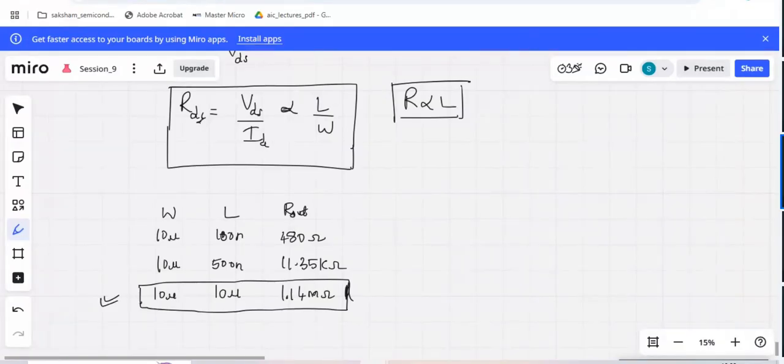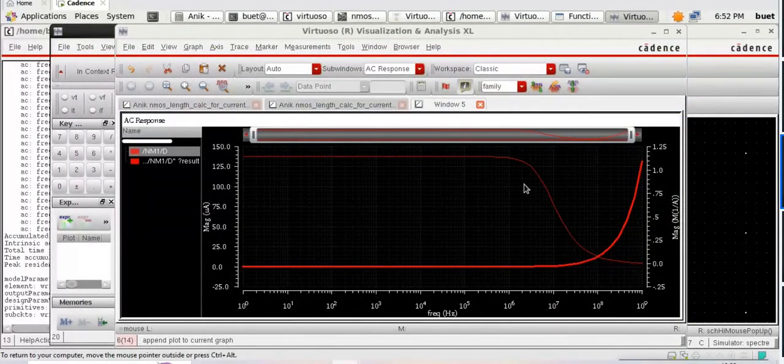Now the reason behind this is, I cannot keep on increasing the L. The moment L increases, the output resistance changes. The intention of this exercise is to ensure that for all the frequencies from 1 to 1 gigahertz, the resistance should remain the same. But what has happened? The resistance started to dip over here. So this should not be the scenario.